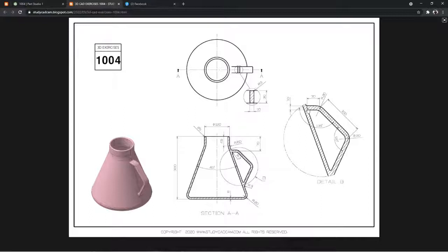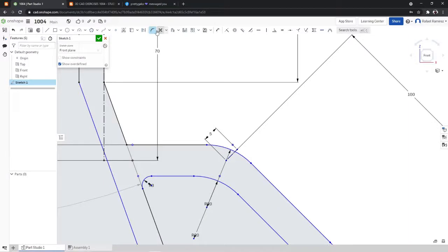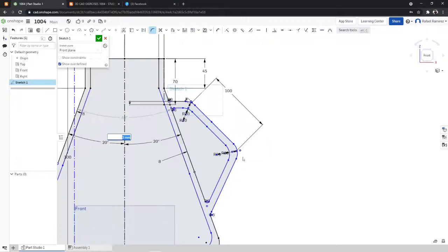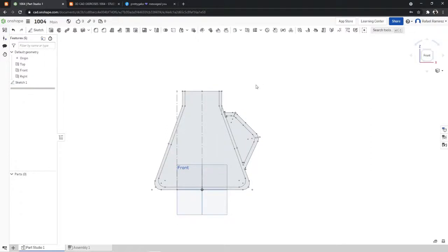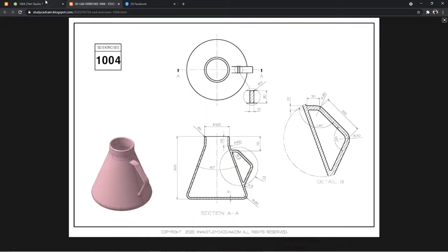This needs to be also 3, because that will be 3 here, and 3 here. It was not indicated, but as you can see, since outside fillets need to be 3 millimeters in order to have a balanced handle, this needs to be 3 also. Alright. So the figure is already done. As you can see, if we click on check and compare it to the drawing, we have followed the same specifications on the drawing here.